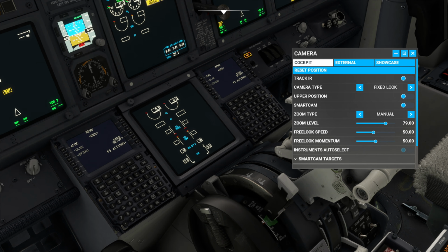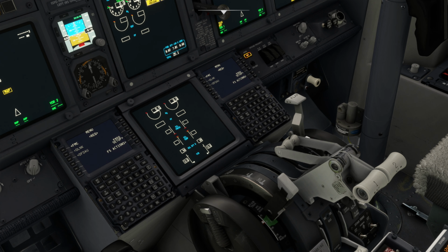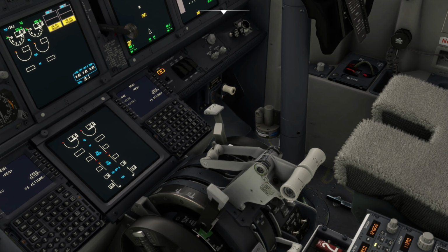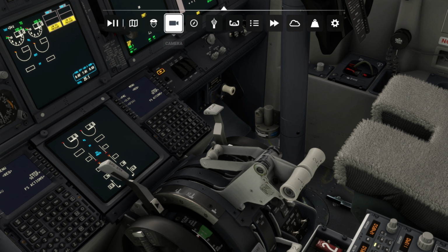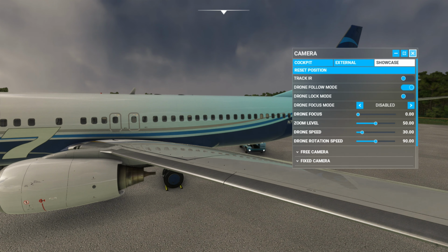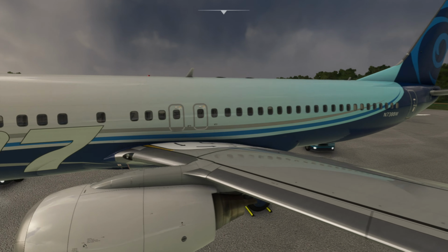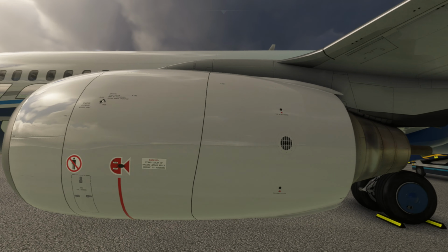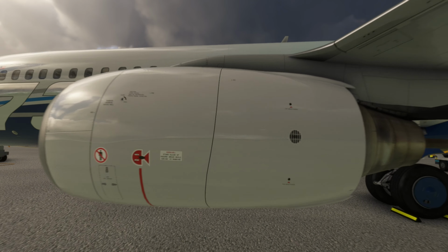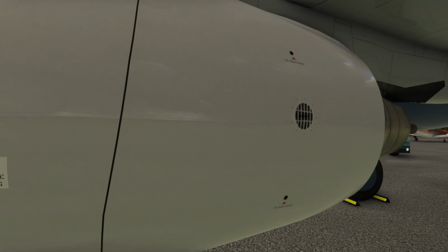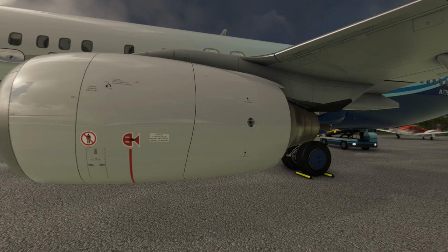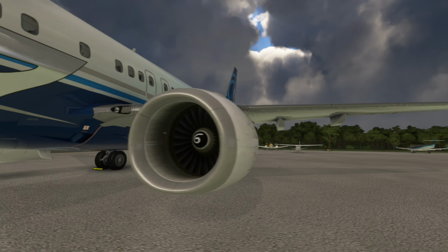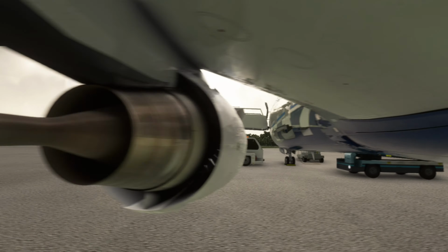Very important. They will also be operated in conjunction with thrust reversers. The thrust reversers are, on at least the 737-800, panels that come out from the after portion of the main engine nacelles. You can see that we have this very conspicuous shut line on the main engines. This will break rearward, and the after portion of the nacelle will transit rearward longitudinally, allowing the engine thrust to be redirected from the aft portion of the engine here.